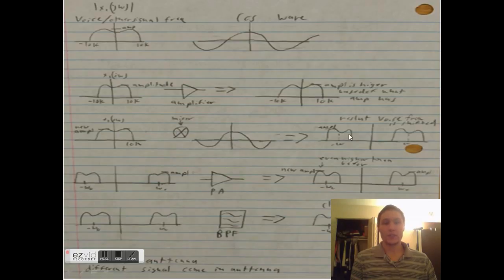Now, when you send it through the mixer, it's going to be a phase shift right here and right here, both in the frequency domain. It's just moved over by omega naught and negative omega naught. That is the frequency of your carrier, your cosine.